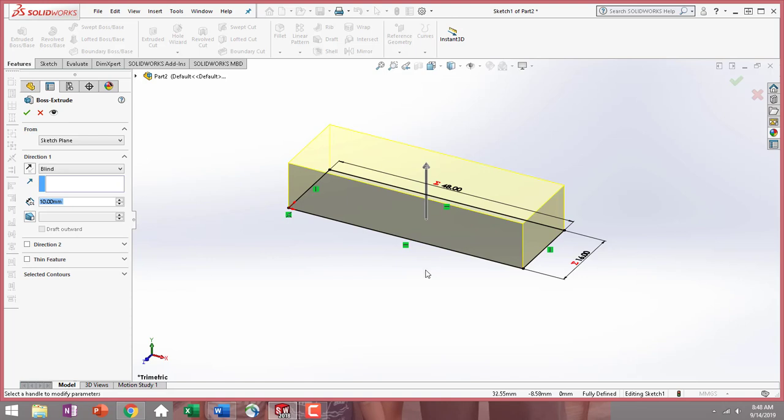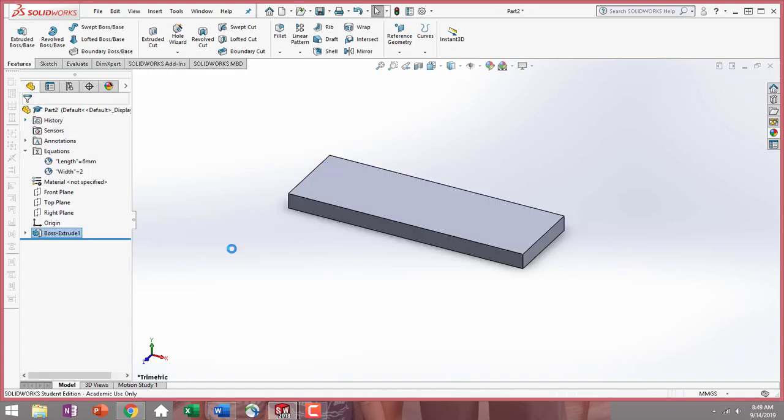Remember, we wanted our extrude to be up, and our distance down here, we're going to change to 3.2. This is going to be the basic overall thickness of your Lego blocks. So if you get lost, you can go back to this tutorial or this milestone and see what your basic dimensions are for most of your bricks, because they're all going to have to be shelled the same. The knobs all have to be the same diameter and height so they all fit together smoothly.